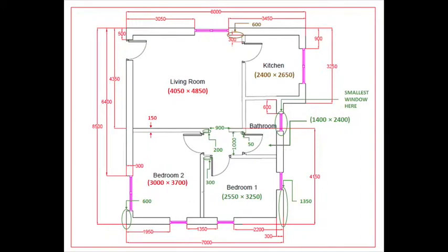I also assume that the opening between these 2 points is 900 and the small protrusions here from the walls through the jamb of the door, I assume at 50, and these two partitions, I assume at 200 and 300 respectively. From these assumptions, we can derive the width of the hallway as 1 meter and the sizes of the bathroom and bedroom 1 as I already mentioned.